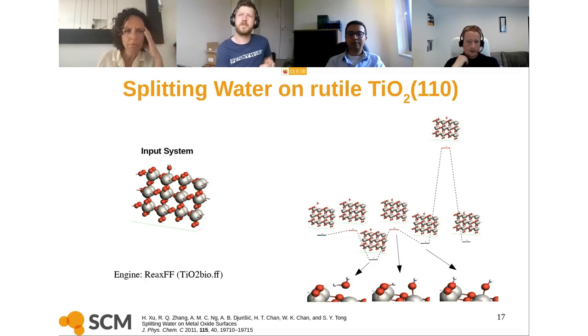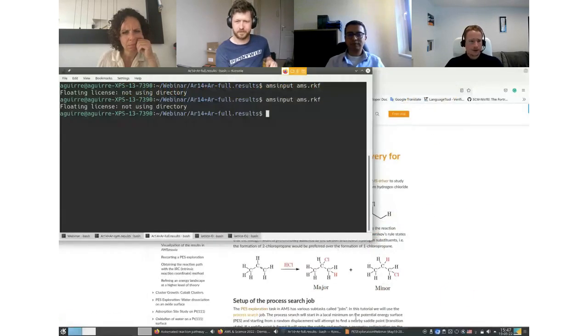It seems to be the way to go to do that with plane wave codes, because they provide a more evenly spread basis, or a generally larger basis, if you will. And that seems to matter in that case. Also, you have an easier time enabling smearing and things like that. So usually one would do that within AMS with Quantum Espresso and the interface we have for that.